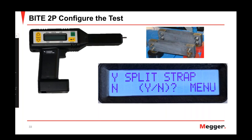So you can see in the picture that we have a split strap situation where you have 2 straps for the same post. So the way that this works is, let's say that you have 4 battery straps and you can only get the CT around 2 of those straps. What you're going to do is take the total number of straps and divide it by the number of straps that you can get that CT around. So 4 divided by 2, your multiplier is going to be 2. Go ahead and enter that value into the receiver and push the enter button.